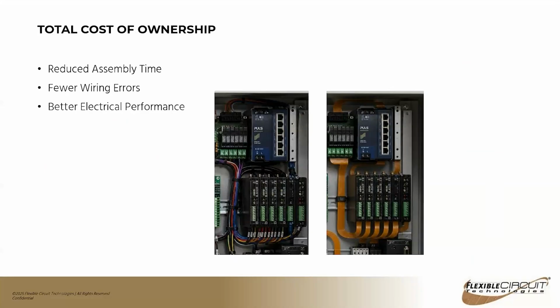When we think about flex, it's important to think about the total cost of ownership. If you compare the cost of a wire to the cost of a flex circuit, just on the surface, of course, the flex circuit's going to be a little bit more expensive. But when you factor in the reduction in assembly time, you no longer have an operator taking all of those individual wires and plugging them in. Fewer wiring errors. You don't have to worry about somebody putting a red wire where a white wire belongs.